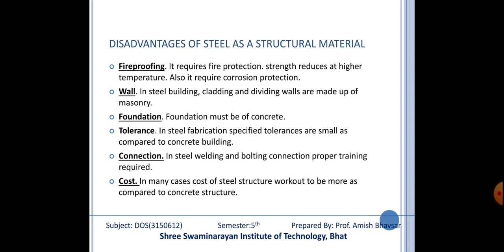Cost. In many cases, the cost of steel structure work comes out higher as compared to concrete structure. Means, as we discussed, steel is a lightweight structure as compared to RCC. So the weight is less, then dead load is also less, and the members can be smaller as compared to RCC because weight is less.